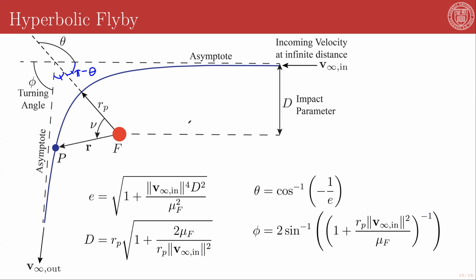This is really significant in cases where the body that you're flying around has an atmosphere or has a significant magnetosphere or magnetodisk, like the gas giants and especially Jupiter. Things that can be hazardous to your spacecraft's health if it gets too close, which would lead you to limit the closest approach. Similarly, V infinity is related to energy and therefore is a really good proxy for a full description of the orbit that the spacecraft is on when it enters the vicinity of the flyby object.